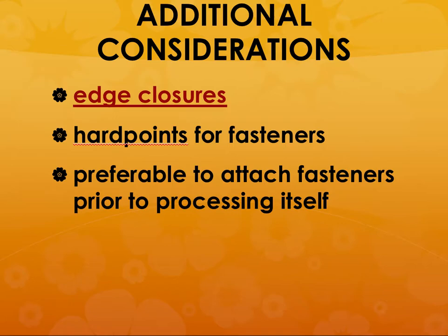And additional considerations are that suppose you have to fasten something or you have to bolt something, you have to ensure that the bolting point or the hard point for the fasteners do not damage the sandwich structure. And the way you do it is you have to attach the fasteners prior to the processing itself, so that you are not creating any kind of weak points into the material after the part is cured.